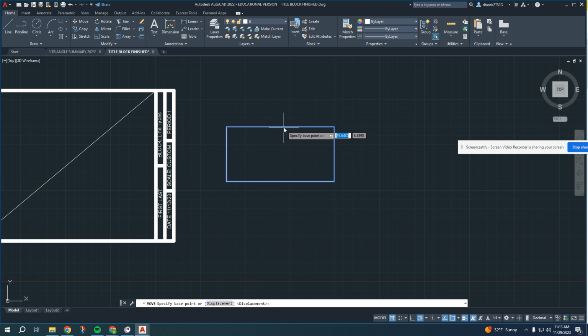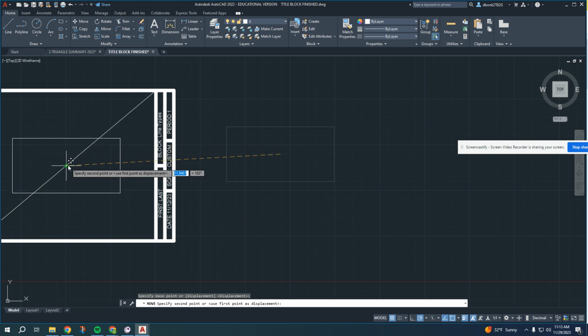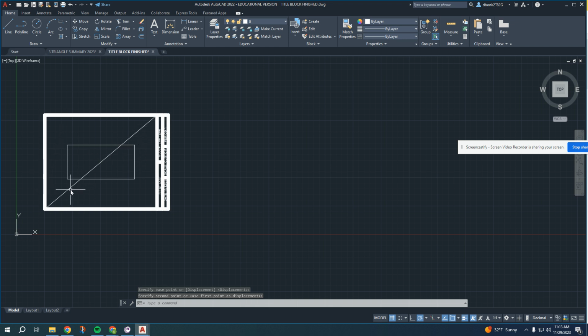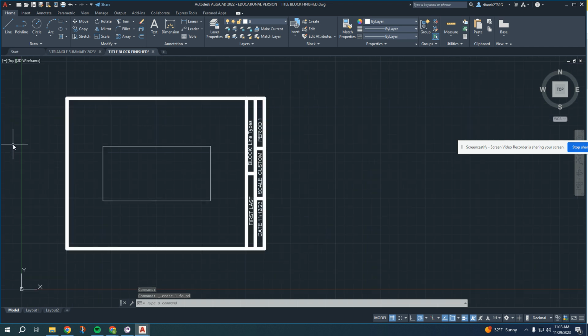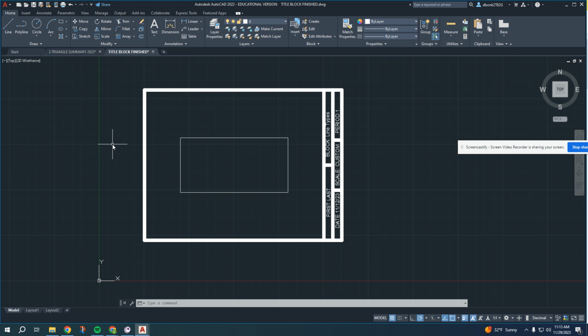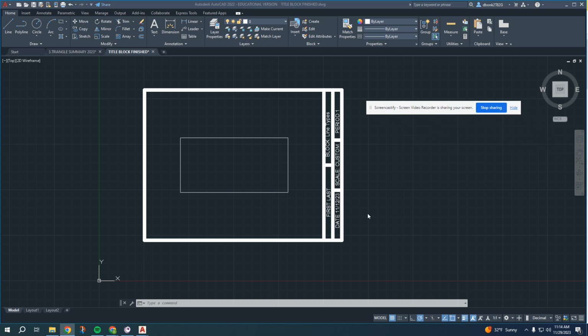And what you're going to do is you're going to find the middle by going over one side, midpoint, and then the opposite line, vertical and horizontal. And you go to the middle of this rectangle and find that X, click, it'll pick it up from the very middle, and then you can take the very middle and place it on that triangle, and you have a perfectly centered box that you can work with to center your drawings. Some people's drawings are all over the place because they're not being centered the right way. So that's why I'm addressing this way. Whatever drawing it is, the field, the 4x4, the triangle summary, they all start off with some sort of centering of a box. And this is a much faster solution for you guys to use as you work.